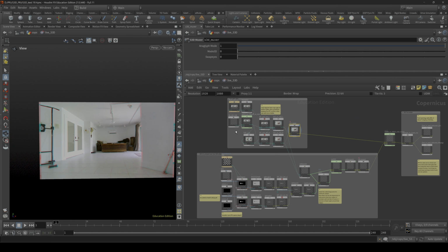If we look at I'm collecting geometry from the left and right camera, let's go up to our object level view here, and you can see here, I don't normally use the stereo camera rig here in Houdini. I usually make my own. I prefer to do that. And cameras in Houdini are a bit odd anyway, because they don't let you move a backplate. They move the lens and then offset from there, which is difficult to deal with when you're doing deep compositing.